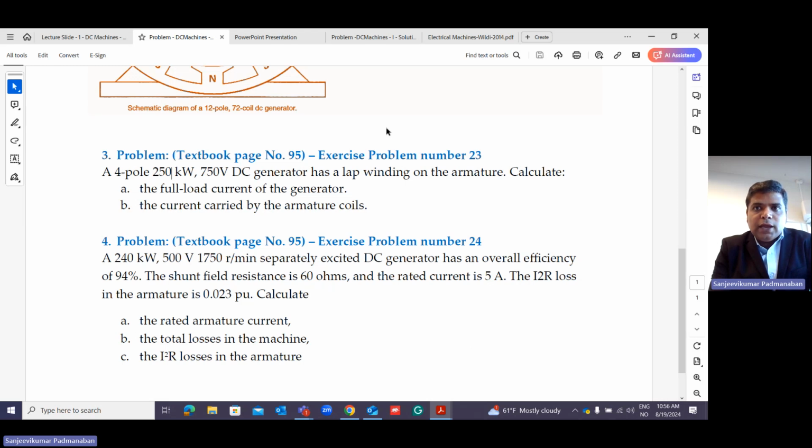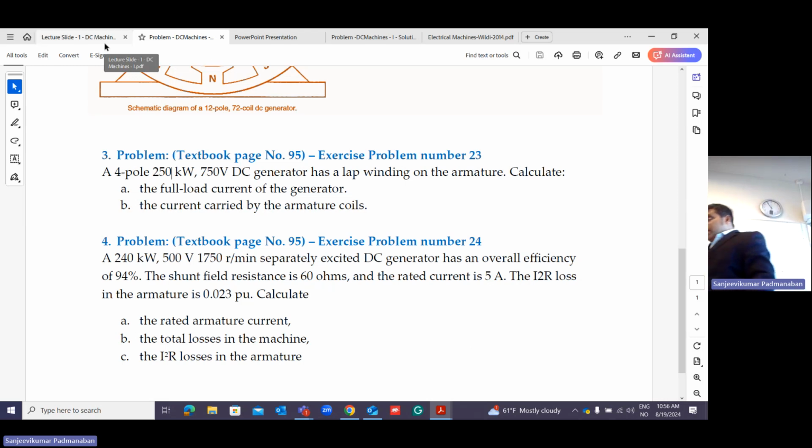The last problem, we will look at after the theory. Let me go to the next slide. All finished. Please write in your answer how to calculate the current through the conductor: the total armature current divided by the number of brushes, not the number of brush sets. Look at my diagrams. A set of conductors or a set of coils will be connected to one brush. There are 4 brushes. We put 4 different brushes and pair 2 as positive, 2 as negative. But I'm concentrating on how much current one set of conductors is going to take. So divide by 4.